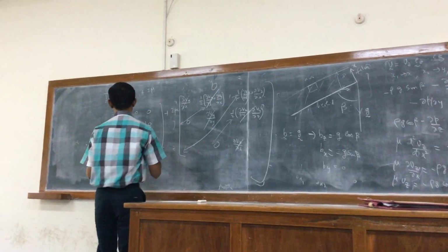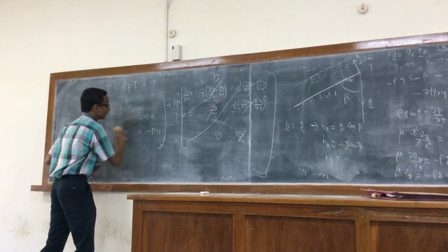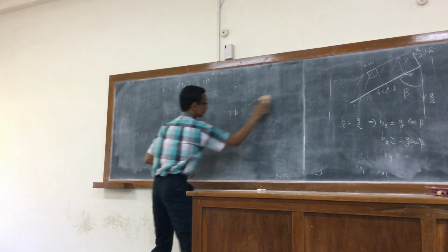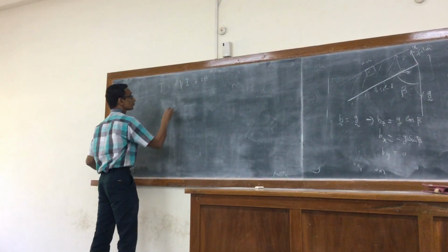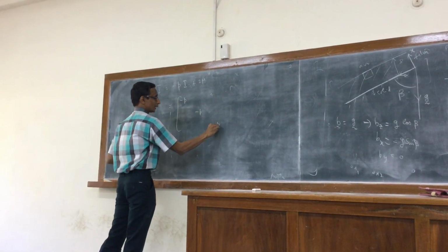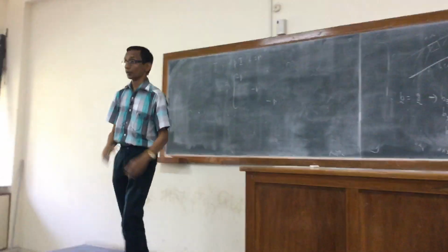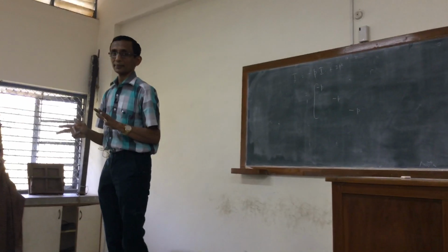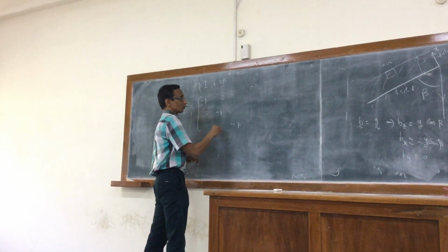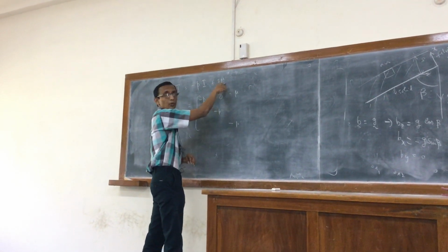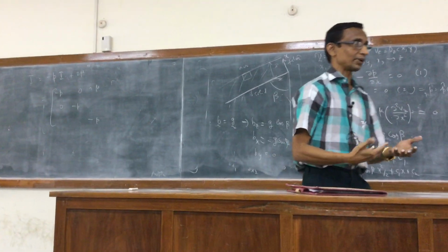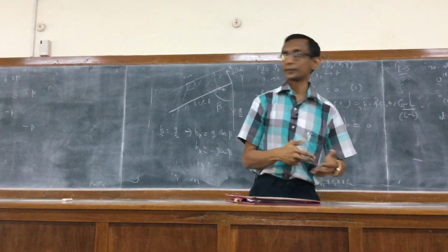Right? So clearly now I can write the stress itself as minus p along the diagonal. This is now the entire stress tensor. So this would be 0, this would be 0, this would be 2 mu times, I will have half dvz by dx, because dvx by dz is 0.